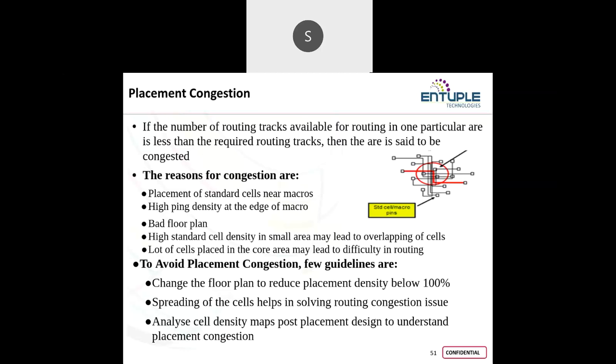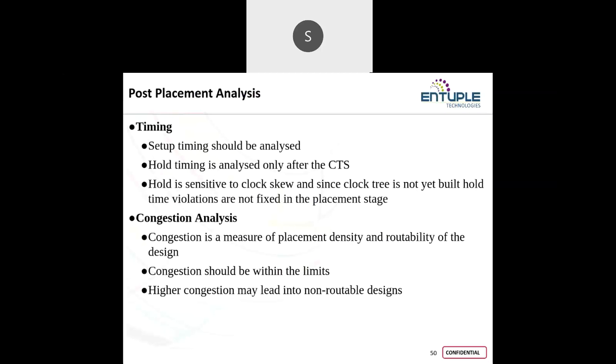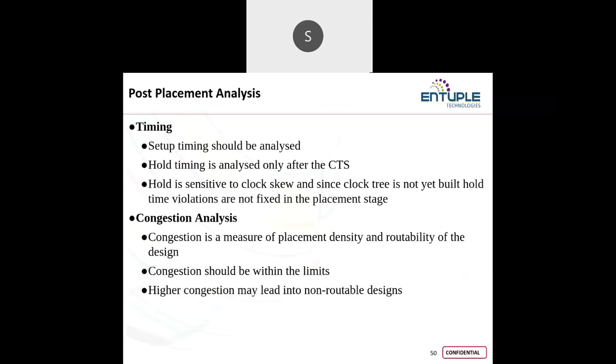Once that is done, from the placement stage onwards, I have the option to check the report with respect to setup violations in the placement stage. If I have any violations with respect to the clock, I am ignoring them, as I have already told you, because we are not using the actual or propagated clock signal. I am using the ideal clock signal, so I am only worried about the setup violations, because the data path comes into the picture with respect to setup.